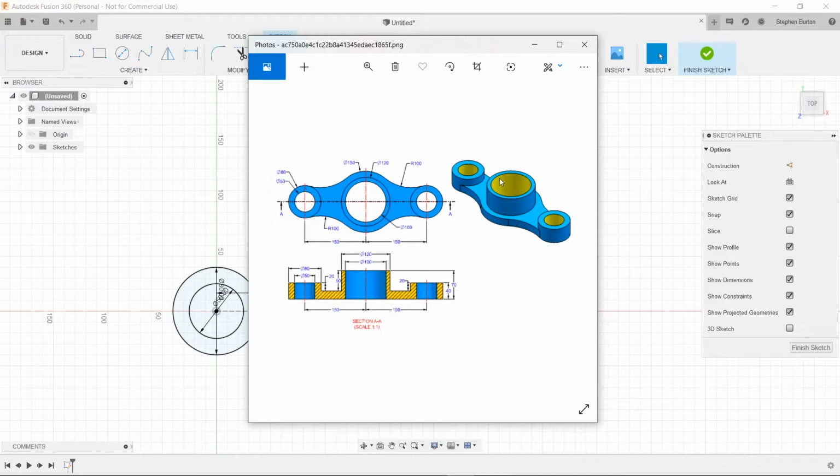Now if you notice real quick, just on a quick tangent, there are several circles in here of different heights, and you think, well, if we draw all of those in and we extrude it, then once you extrude it, you're going to lose all that sketch, and then you won't be able to extrude these further, so you'll have to redraw them. So why would we draw them in the first place? Well, I'll show you how, but we can actually go back into that sketch and re-extrude things multiple different times, so that way we don't have to be worried about losing our sketches. We can draw in everything at the same time and do multiple extrusions from one sketch.